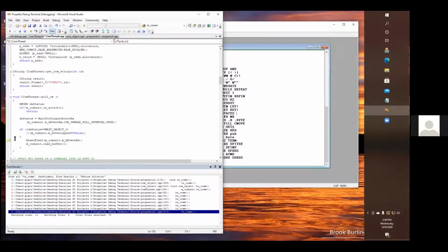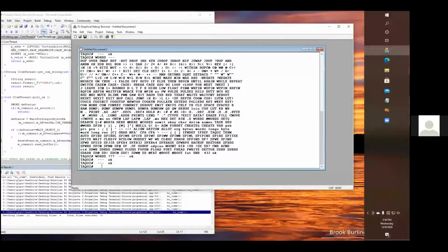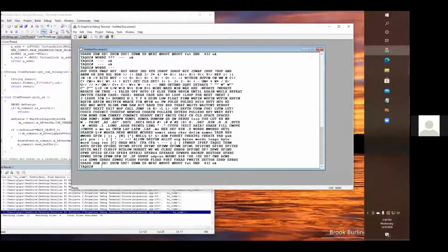And if you imagine that firing 190 times or whatever, did I hit F5? I'm going to get running again. 1, 2, 3, 4, 5. There we go. Serial ports can be brutal to debug because you're asking it to pause the thread. Wish me luck. Oh, we didn't get it that time because I confused it with all those breakpoints. But there we go. Now we're getting it. Okay, and that's those 192 buffers being cycled through, right?